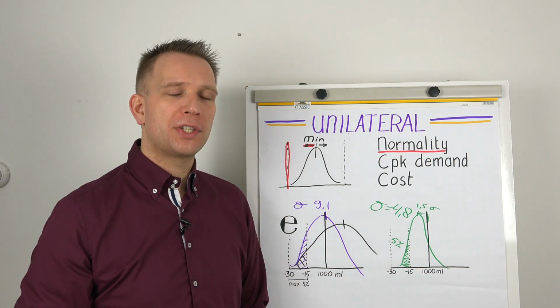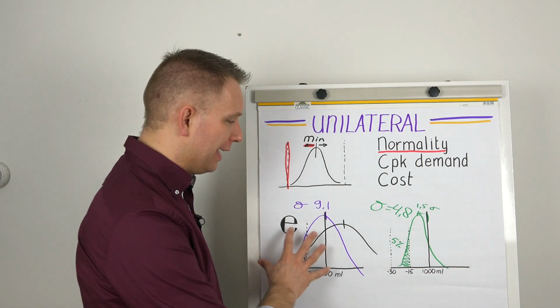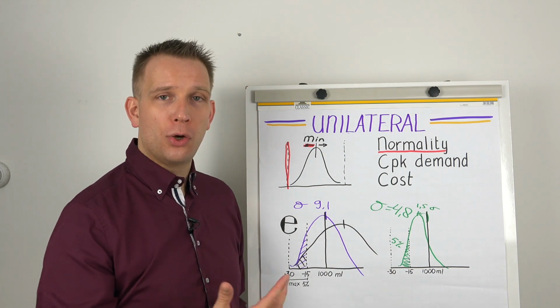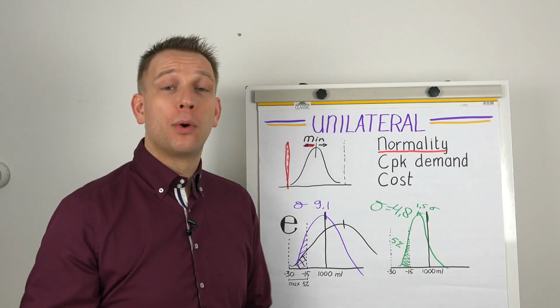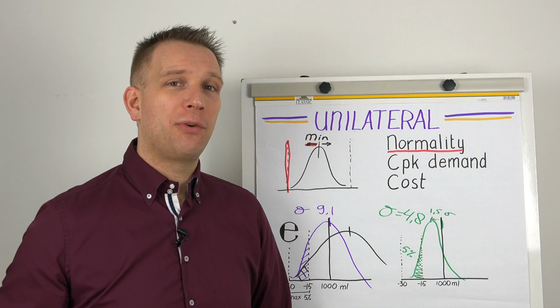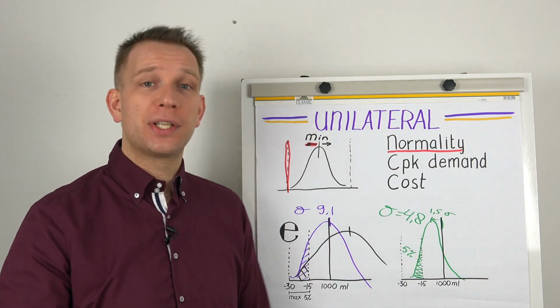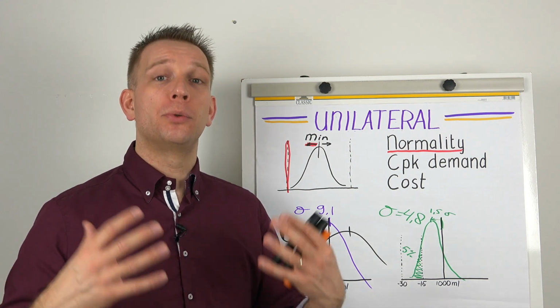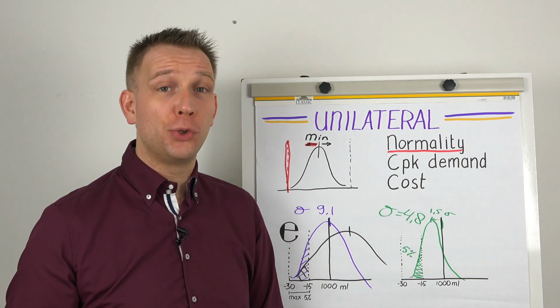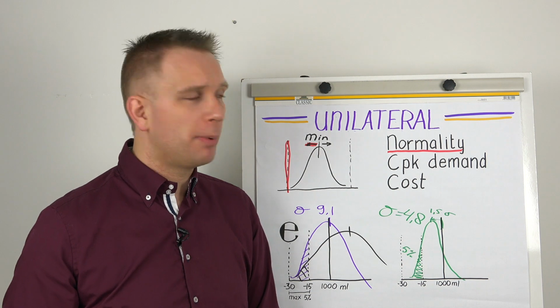It's a different question where we will have to use information that our laws or customer provide. Maybe they provide a direct CPK, but more often they will tell it to us in slightly different ways that we have to recalculate back into what level of standard deviation do I need, when is my process capable.